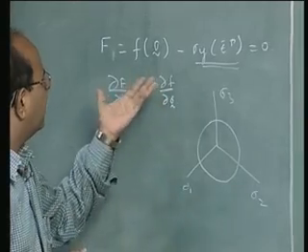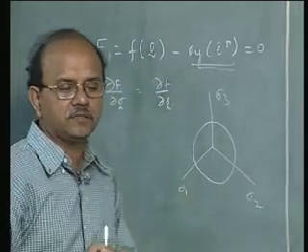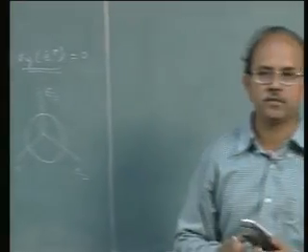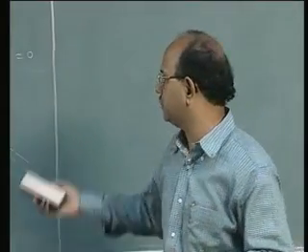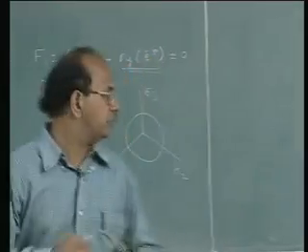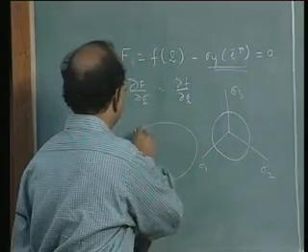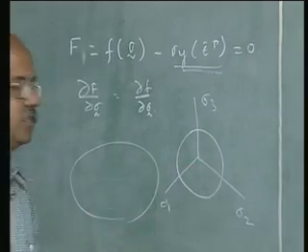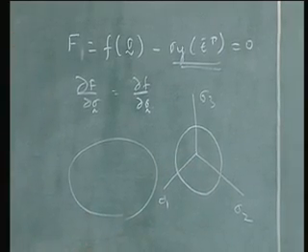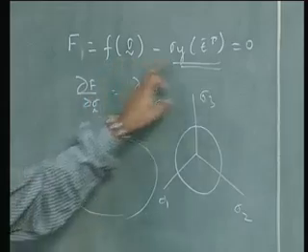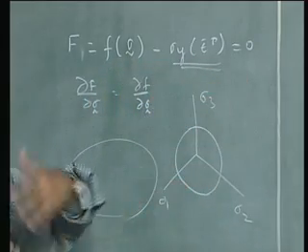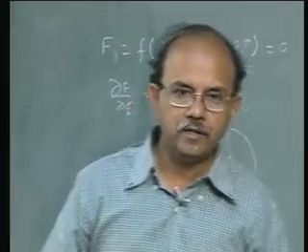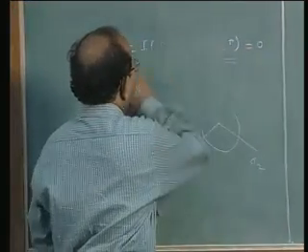It is not necessary for you to imagine this; it is only of notional value, to make it easier to understand. We were talking about the yield surface to be like this and so on. It may be very complicated, but this can help you a bit to understand what it is. So this mathematical representation is converted into a geometric representation, and that's what we call the yield surface.